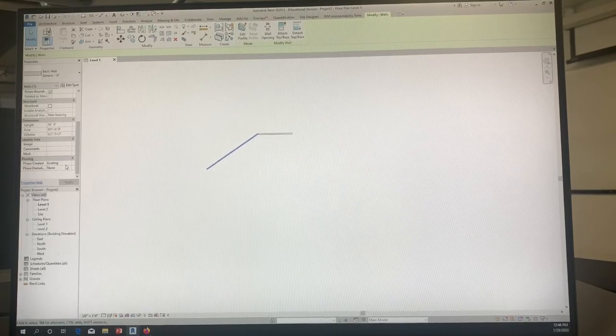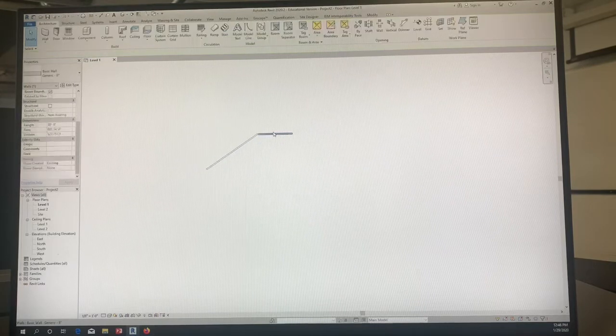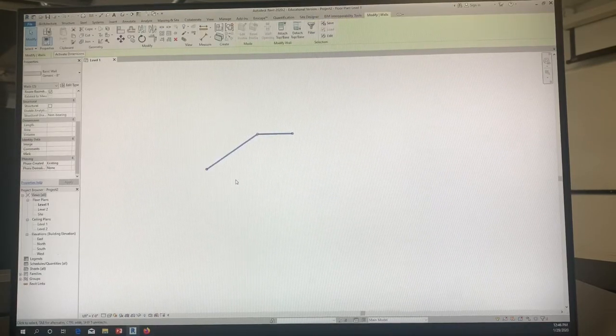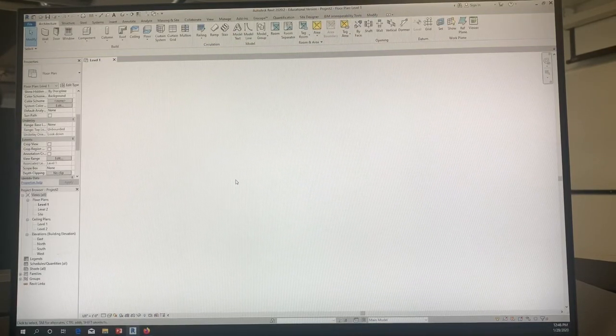And that's for your as-built drawing that you're doing. Every element that you put in there must be on the existing phase. Everything, including the walls, the windows, the doors, toilets, all of those elements should be on the existing. So that's where I want you to make sure you begin. Okay, so I'm going to delete that. You can go ahead and save this and call it assignment 2. Okay, but that's where I want you to start from.